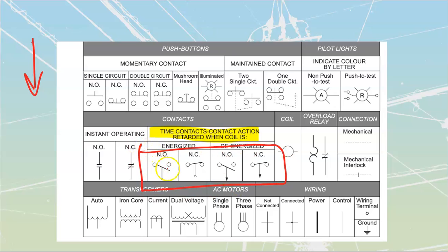Looking at these, I see that that is a normally open, just looking at that bar. Looking at that, I see it as a normally closed. This one is a normally open, and this one is a normally closed. So I work off of those, the NO and the NC, and then I define what they're going to do. Now, we don't cover these a lot in this year. We will cover them in subsequent years. But the direction of the arrowhead tells me about when I'm either turning this thing on or turning this thing off.